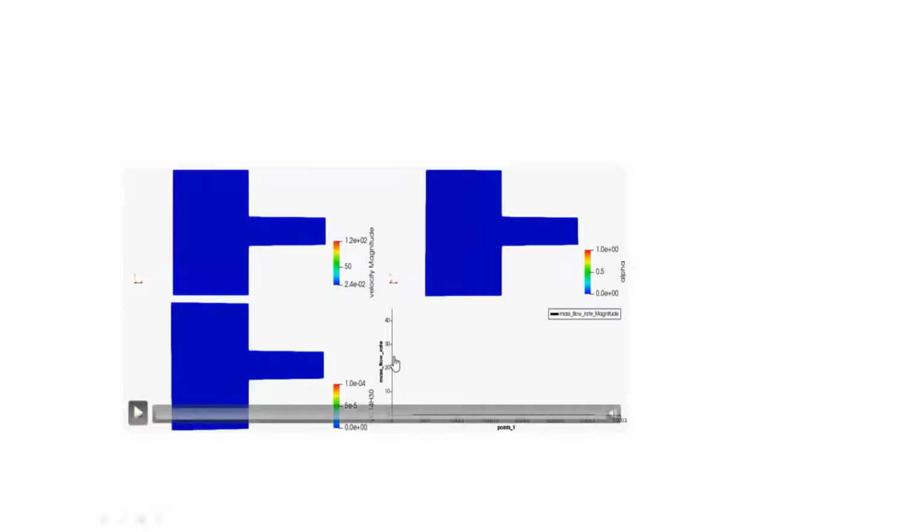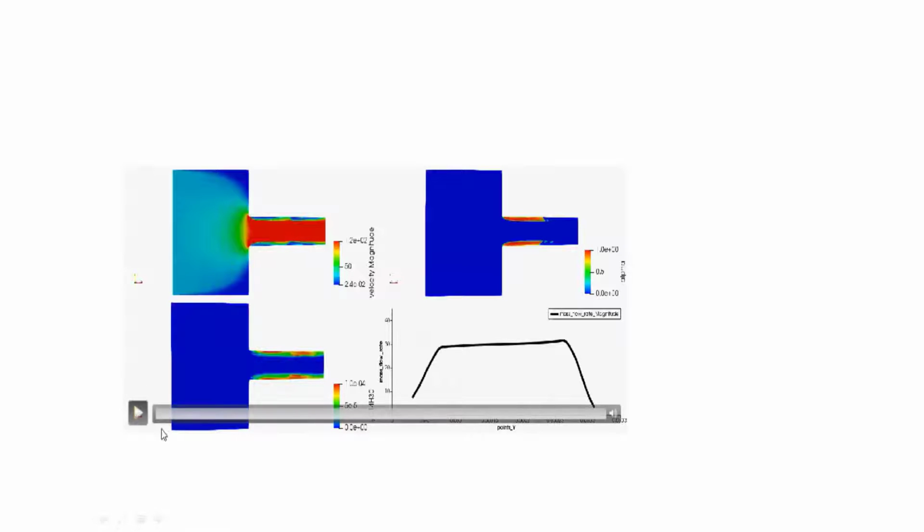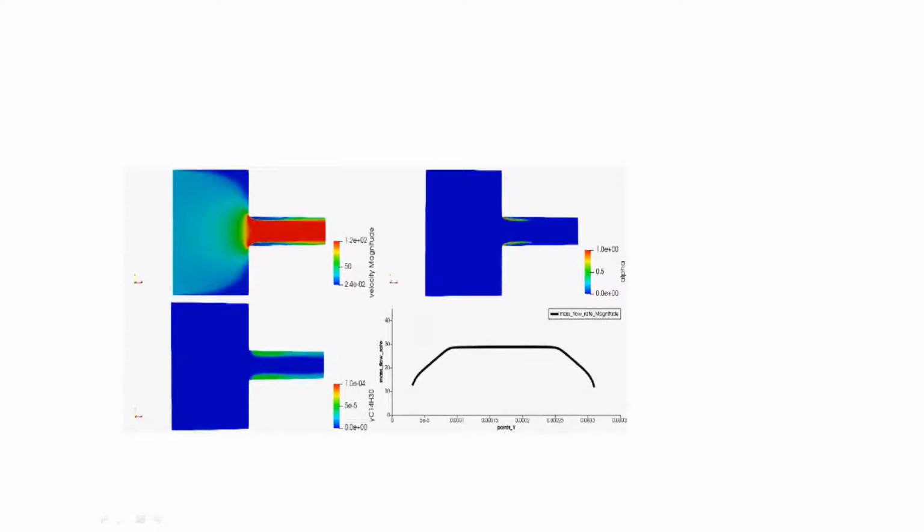This is a 2D cavitation problem, a multi-phase problem, where air is there and liquid is also there, and this is the Winkelhofer nozzle, which is used in diesel injectors and all. If I play this, you can see the animation, right? Here we are seeing how the mass flow rate is continuously changing in a rapid manner, how the void fraction is changing, and how we are able to capture the physics here. Right? So again, I'll play it. You can just take a look.